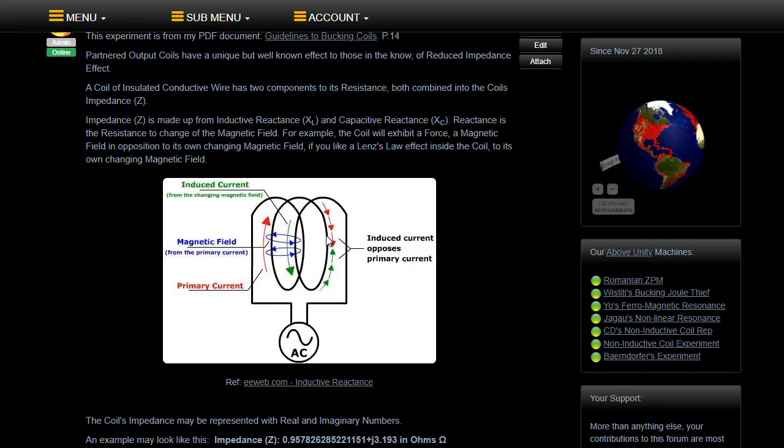Back EMF typically is between 1 or 2 coils, and in this case we can see 1 coil. As the AC sine wave source is applied across the coil, as the voltage changes, the current changes in the coil. The change in current creates a voltage, which they call induced current here, but the induced current can only flow if there's a voltage that's induced as well.